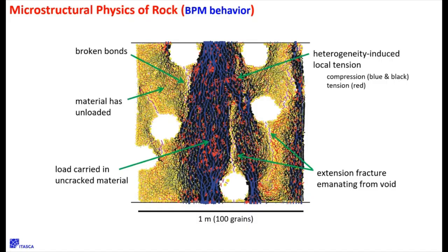You don't have to have, these particles could be polygonal, and now they're going to be more interlocked. And so that's going to affect things, right? These particles don't have to be bonded particle models. Each of those particles could be a little triangle that's part of a big finite element mesh of a continuum, and you could have those interfaces breaking.